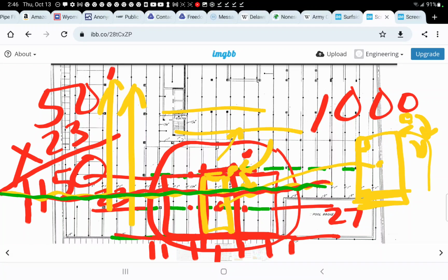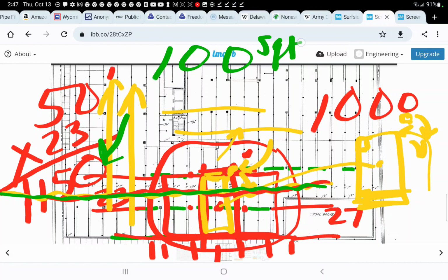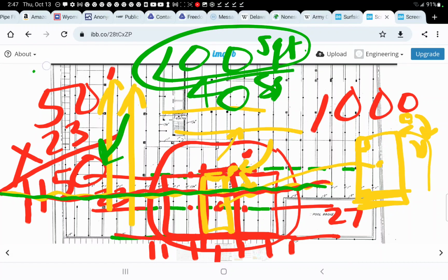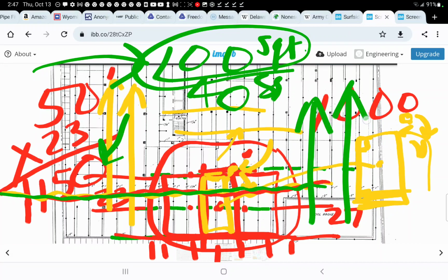Okay, so this 1,150 square feet I came up with, surface square feet, and you add the 2 layers, the base deck and also the overlay, and just throw it up at 100 square feet. That damn thing's a foot thick, right? Plus the tile weight. So it's 100 pounds per square foot. The deck was designed at 40 pounds per square foot. So you're already overloading it. I know a couple of people say, you're right there. When I put steel in and start playing around with steel, it gets very close to almost being able to do it. It doesn't do it.